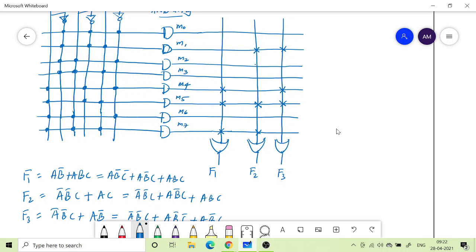Like there may be something like a fuse which you need to blow up basically. The other is anti-fusing, where you basically join together. So there are more versatile ways of doing it. Like you may have a transistor between these 2 points. The way it is going to implement those connections can be of different kinds. For example, if there is a transistor between these 2 points like this, it is intended for connecting these cross lines.